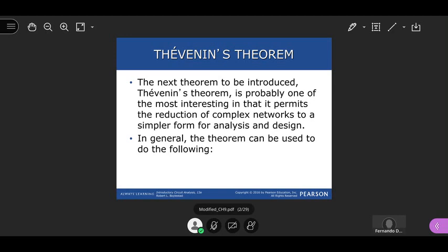And why will you do this? Well, for this case, you have a circuit, like the same circuit that we saw before, that we just solved. And you remember that R4, sorry, R3 that I didn't see at the beginning. Let's say that if that resistor changes, we have to reanalyze the whole circuit again, the same thing that I did. Just because I forgot that resistor, I have to redo almost the whole analysis again.